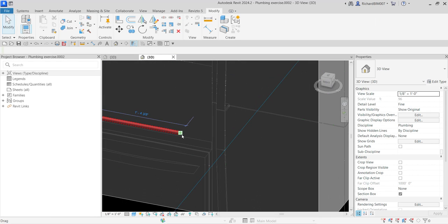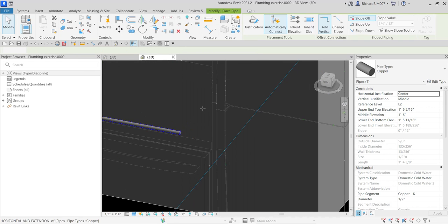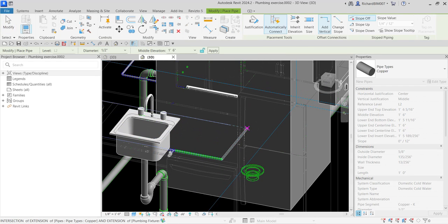So I'm going to click this, right click, draw pipe. Okay, going here. I'm holding the shift so that the movement will only be horizontal and vertical. Okay, straight. It's like ortho in AutoCAD by holding the shift. If I release my shift, as you can see, the movement is like this.